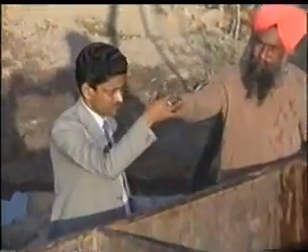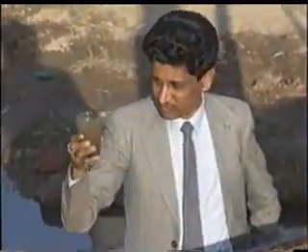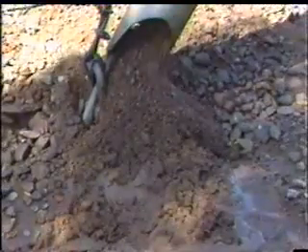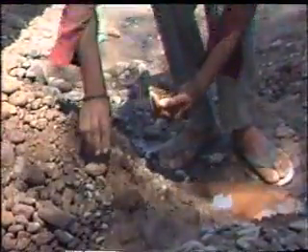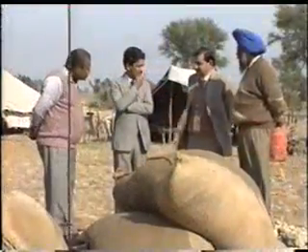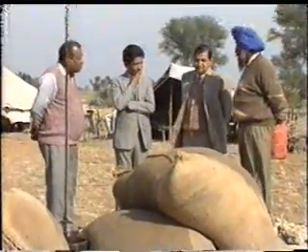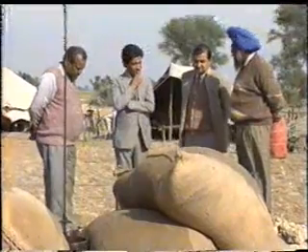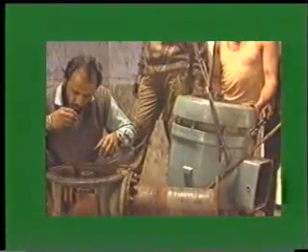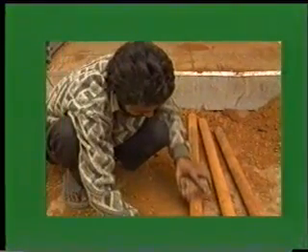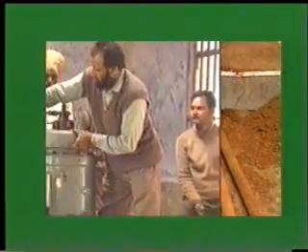If a well gets refilled again with sediment, after bailing, samples should be taken from this well for examination, and expert advice should be obtained for identification of the problem and for rehabilitation of the well. Thus, timely maintenance action, properly worked out to overcome specific problems in a given locality, can improve well performance and increase well life.